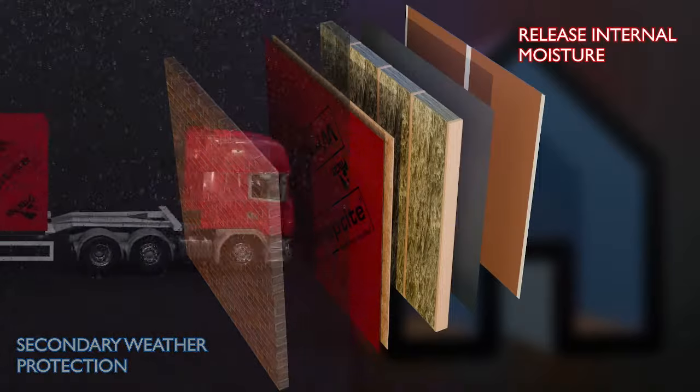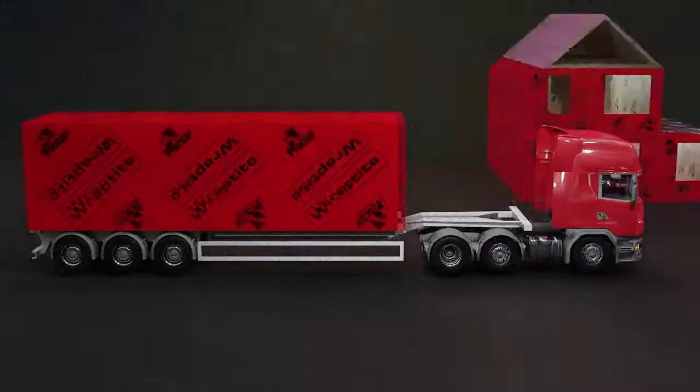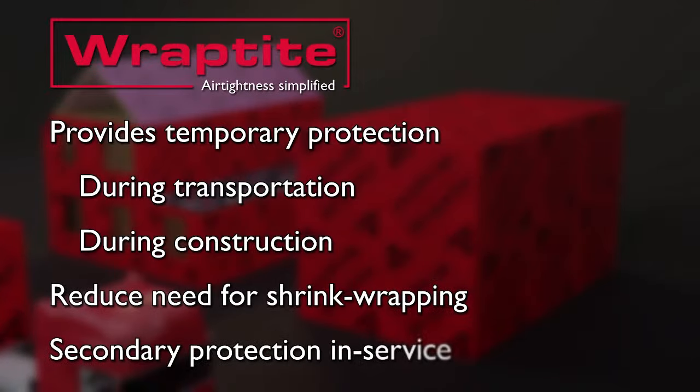In the case of modular and off-site construction, this protection is provided during transportation and storage as well as construction itself. A durable self-adhesive vapor permeable membrane such as Wrap-Tight can even reduce the need for covering or shrink wrapping modules and panels, minimising not just panel moisture content but single-use plastic waste as well.